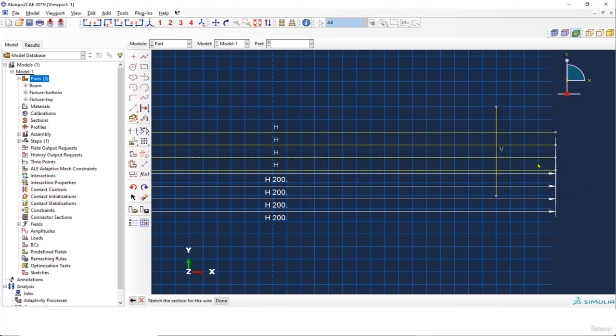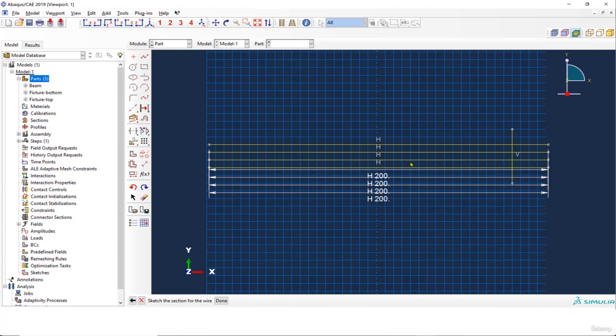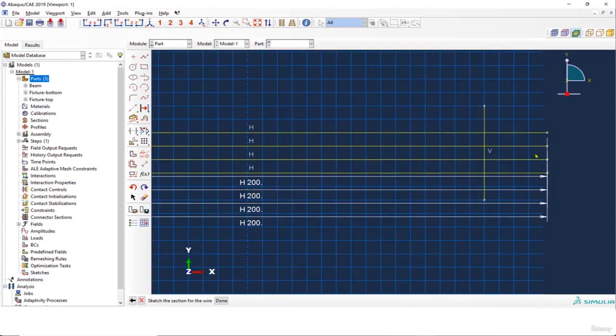Before doing that, I have to make sure that this is going to be in the middle, because I know that the distance from here to the middle should be the same as from here to here. So first of all I'm going to give a dimension from here to this line, and I'm going to make that one 5, and then give the total dimension and make this one 25. Now if I do from here to here, you see that that's 5.